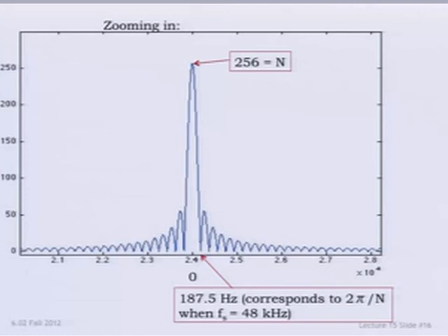So if this pulse is applied directly to the loudspeaker, well, here the loudspeaker passband goes from about 100 hertz to, let's say, 10,000 hertz. You see there's huge amounts of the energy that's not in the passband of the loudspeaker. So this is not going to do very well if you just directly apply that pulse to the loudspeaker. You have to match the frequency content of the input to the frequency response of the system you're trying to get this over.